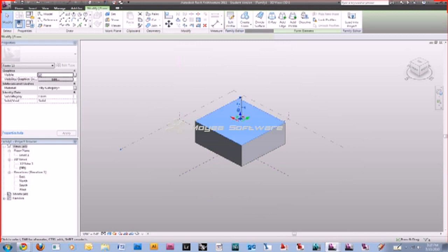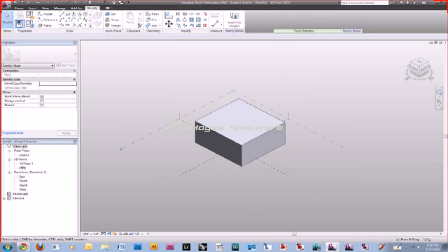The references are probably the hardest thing to understand, but once you start working with them, they're really easy, and they can allow you to perform way higher and more detailed tasks. It's as simple as saying draw a square, and then you make that mass just like before. The way massing works is similar to SketchUp. Nothing against SketchUp, it's a great program, but it works the same way. You start with a sketch, and then you extrude that up into a mass, the way I just showed you a few seconds ago.